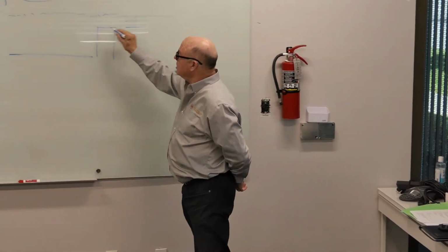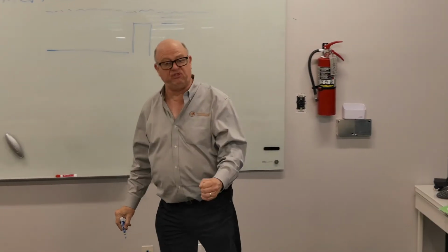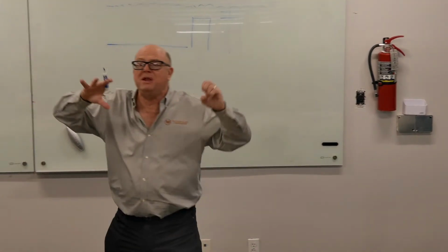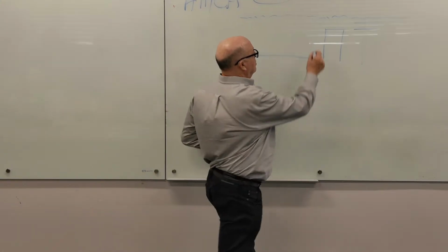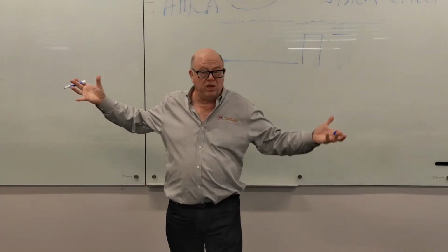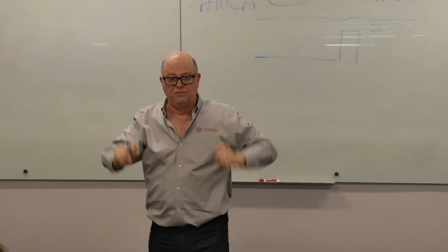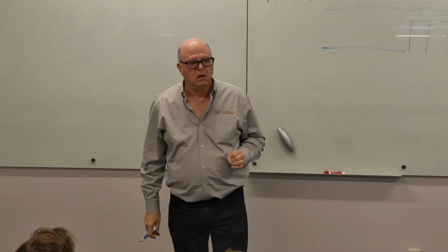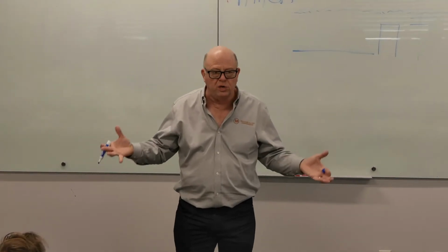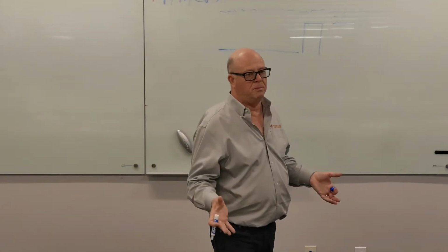Had we tunneled it, which Pete suggested early in the process, it would have been really easy, so that these ducts are going over the top and you don't have to worry about those combination fire dampers. Had we done that, we'd have had about 18. So the difference was about 100 combination fire and smoke dampers.